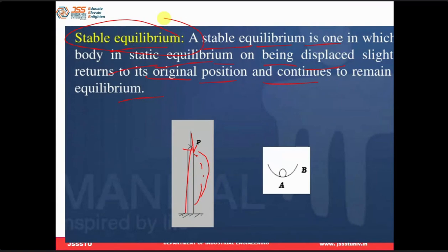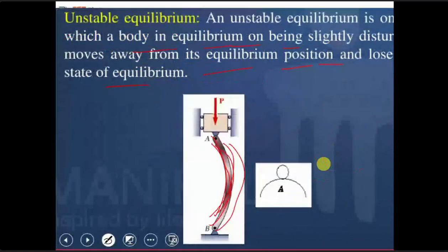The best example: if you take a stick, keep it in a vertical manner, and press on both sides with your hand like this, what happens? It will bend, right? If you apply the load, it will bend slightly, and if you release the load, it will come back. But when you press continuously, it starts to bend more, and at any time it is going to break. That is when buckling takes place.